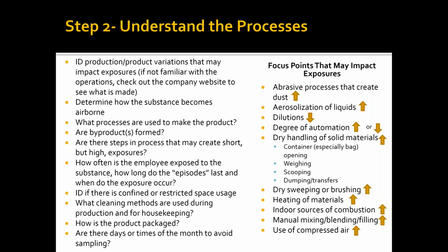Indoor sources of combustion are a big deal with carbon monoxide, especially here up north where buildings get closed up in the winter time. Oftentimes I just carry around a CO monitor with me all the time. And if I see a lot of forklifts driving around, I at least do some spot checks to see if there's an exposure issue. Next slide, please.